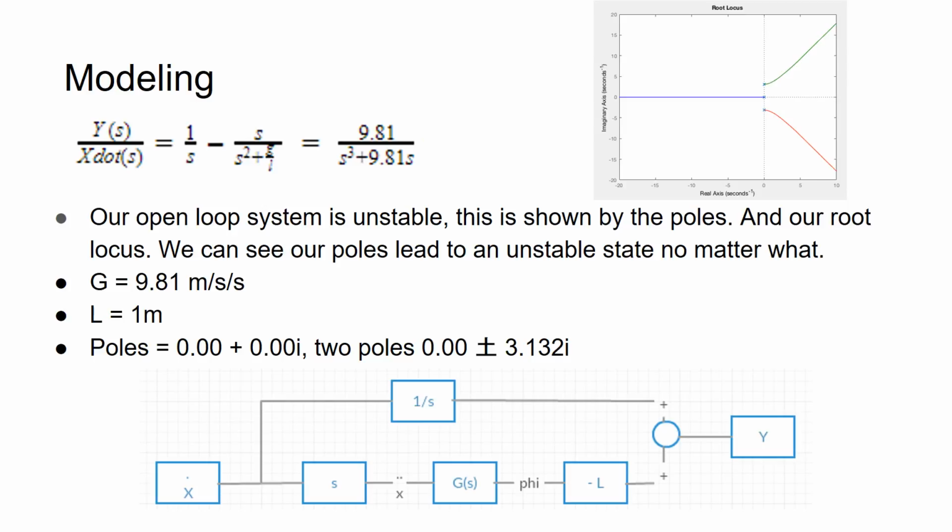Alright, to model our transfer function, we chose to implement a step function. You can see that created here along with the root locus and the block diagram for our function. Using different variables for our function, we set gravity equal to 9.81 meters per second squared and our length equal to 1 meter. We chose 1 meter because with an indoor crane, it won't be very long and we needed to pick a constant value, and 1's very easy to work with.